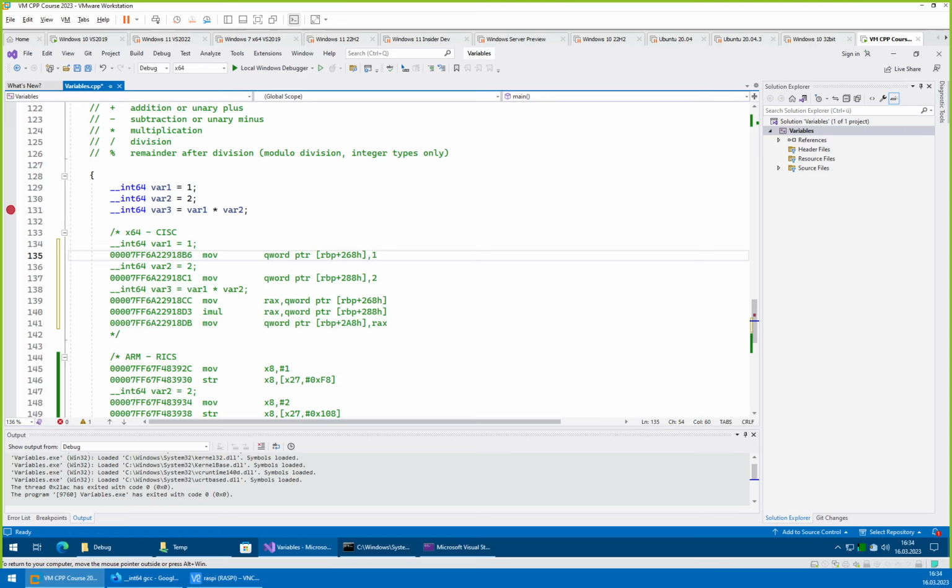And if you have a bigger number which you want to write to a register, then you need to have the number somewhere, then you need to reference the other address. So it gets complicated very quickly, and it very quickly escalates to having more and more instructions to do something. And then you need, of course, a very high memory bandwidth to keep the execution units of your RISC CPU busy.